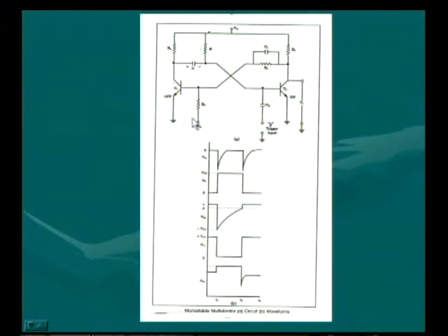And here the resistor can provide a negative bias that is sufficient to keep the transistor T1 in off state with this minus VBB. As we have seen, this transistor T2 is on, VCC will be available here, isn't it? So VCC is this, this is an on transistor, this one is 0 volts. 0 volts is available at this point where it is negative, minus VBB, hence the base to emitter voltage is a reverse bias voltage which keeps transistor T1 in off state.